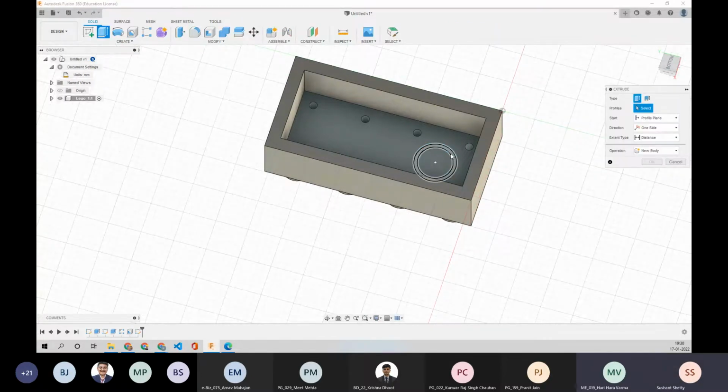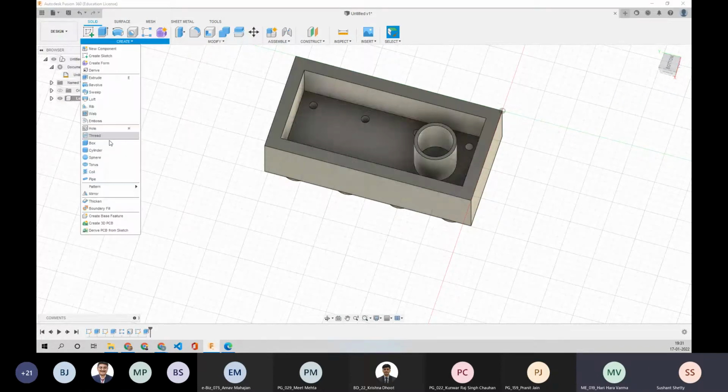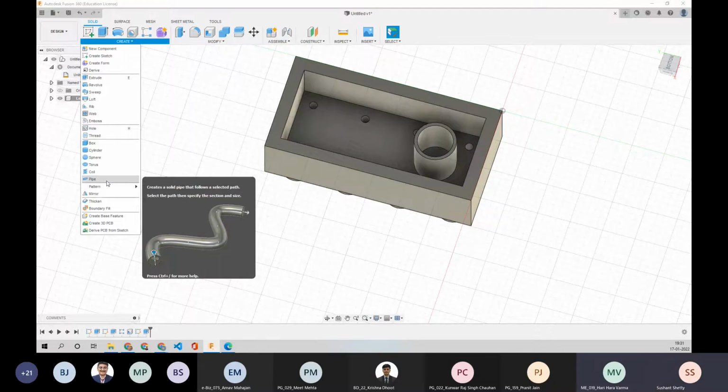And we'll go to extrude. We'll select only this part. So you can see that you can select the whole layer. You can select the inside of this, or you can select this one. And that extrudes to 8 mm. So I click here and you see this has also been created. Now we want 3 of these. So we'll go back to create pattern, rectangular pattern.